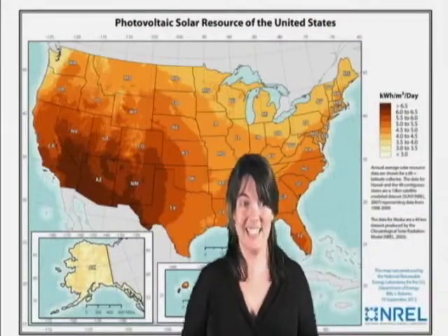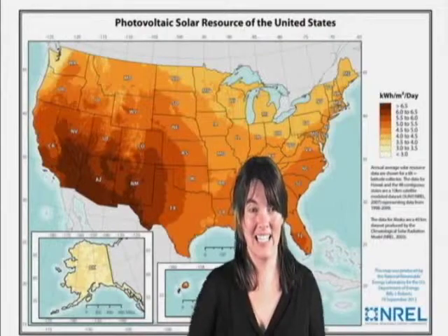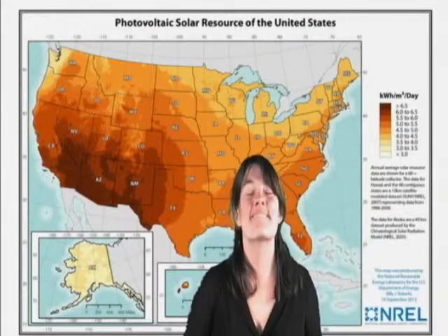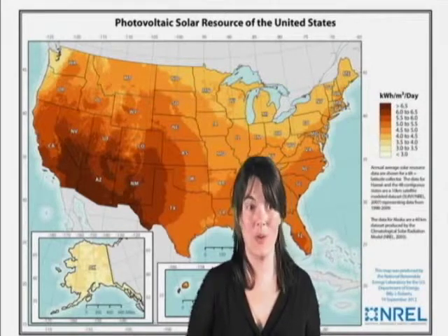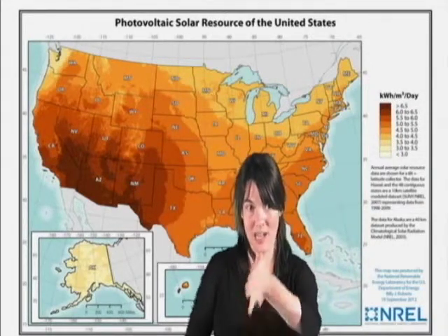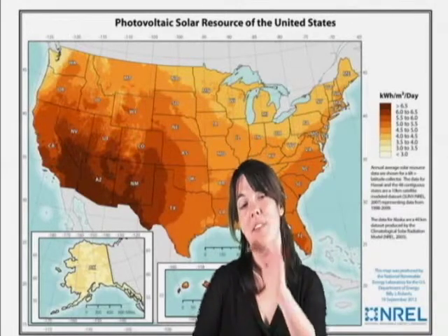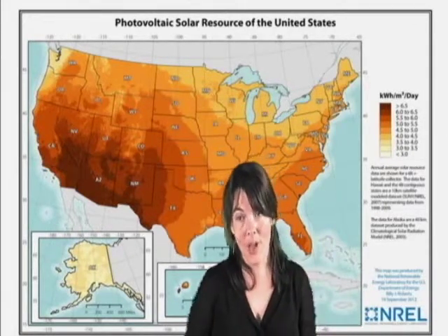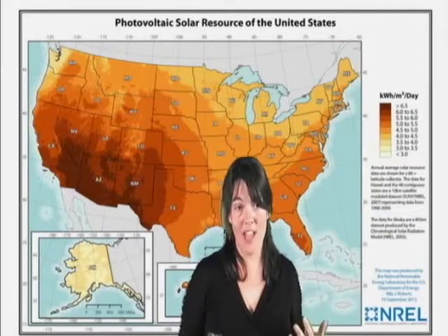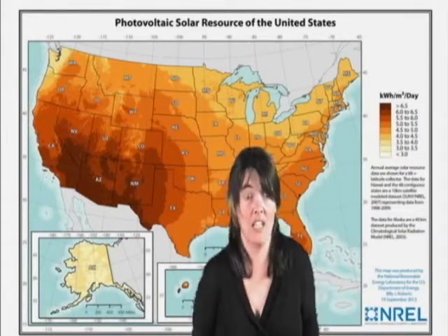Allie, yes, I have a question. To make sure I understood, the colder it is, the more efficient the solar panels are? Correct, yep. The hotter it is, the less efficient. So use that same problem, and put in the higher temperature, and you'll find that the efficiency goes down quite a bit. So when we're looking at solar panels and trying to figure out how many solar panels we need, we have to take into account those average temperatures.